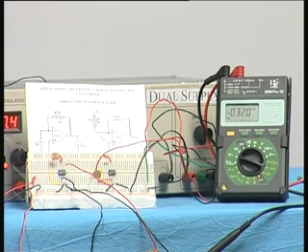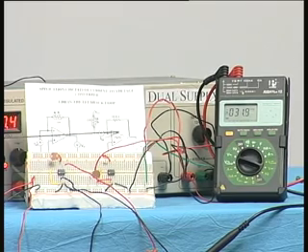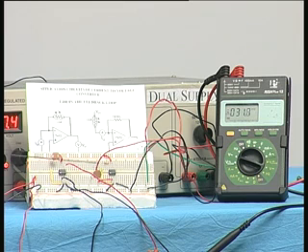There is also another way to get the circuit, and that is, instead of putting it in the feedback, I am using the LDR itself as a current source. So that circuit is shown in the next part of the breadboard. You see another circuit here. You have the LDR now connected to some 5 volts supply. So the 5 volt supply with the LDR becomes a current source in effect, and that is connected at the input, and I put a fixed resistor of about 10 kilo ohm in the feedback here, that you can see.